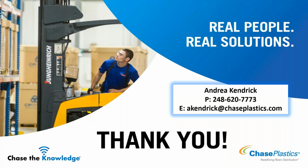So stuff like your PC-PBT, if the PBT is working from maybe a chemical perspective, or maybe it's got electrical properties we're concerned with, or whatever it may be that we picked the PBT for, but maybe it's shrinking too much, maybe it's warping too much, maybe it's glass filled and it's warping too much. The introduction of the polycarbonate that doesn't shrink as much, taking up some of the space within that matrix as a blend now, will lower its shrinkage, and therefore lower the likelihood of warp. And so it's actually really common for materials like that, for PBT, especially glass filled, to add in PC or to add in ASA that's amorphous in nature to combat your shrinkage and warp issues that you may have.